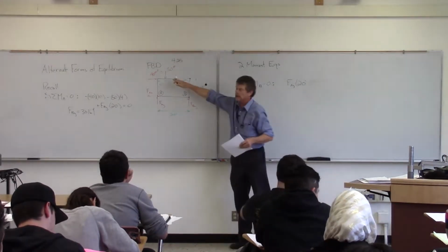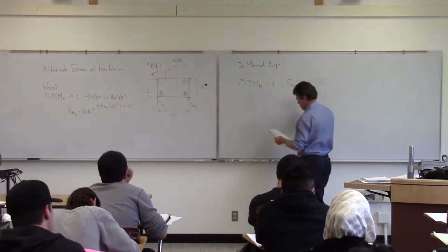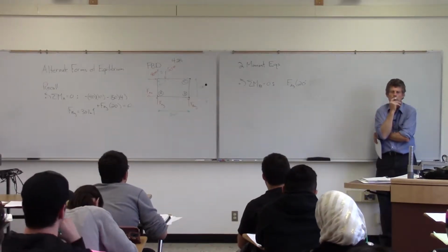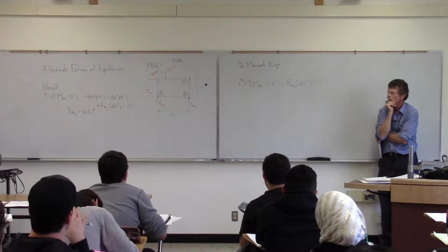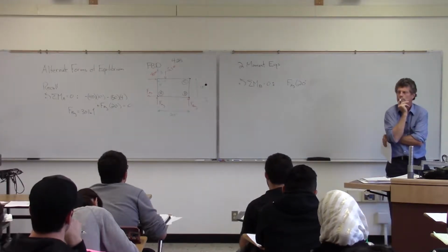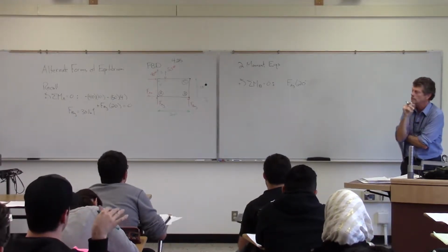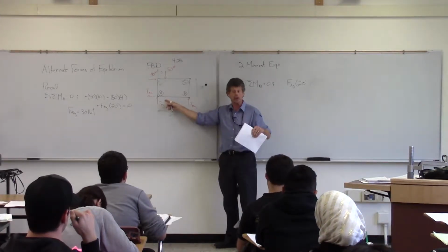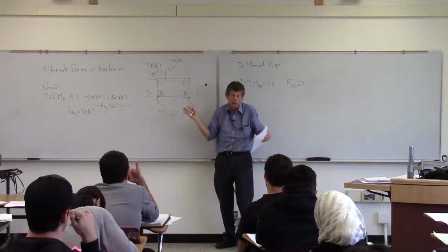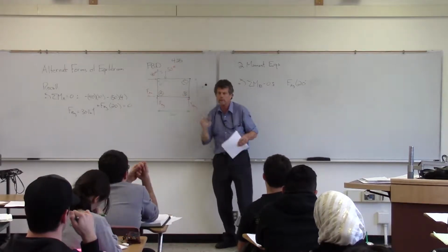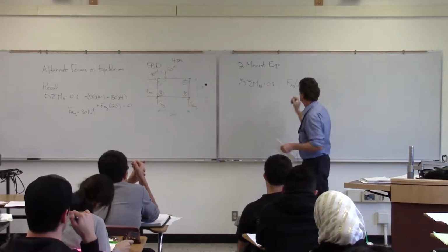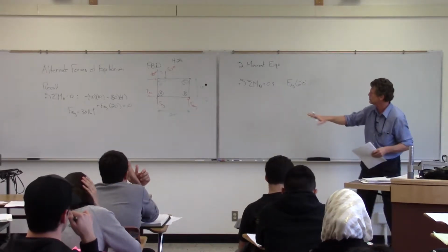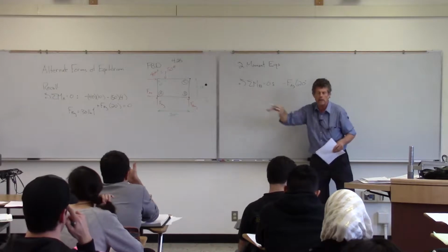Next piece I'll worry about again is the 40. Oh, quick question here too. Positive or negative in terms of rotation? It's going to be negative. We're holding it at B. That force AY, the way I have it shown, is this way. We'll solve for it. If it says negative, then it's going the other way. So I need to pay attention to that, though, in terms of my convention that I've chosen for this scalar equation.